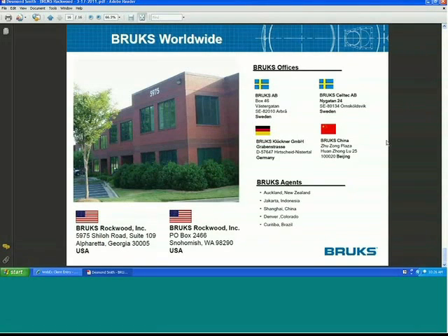Certainly one critical area is the ability to dry, first of all, getting the minimum moisture in the fuel and then drying the fuel without increasing the parasitic load in the system. And I know the new Great River Energy Spiritwood plant is talking about a 66% efficient system using lignite, but using waste heat to dry the lignite, and then also using waste heat for the on-site ethanol plant.